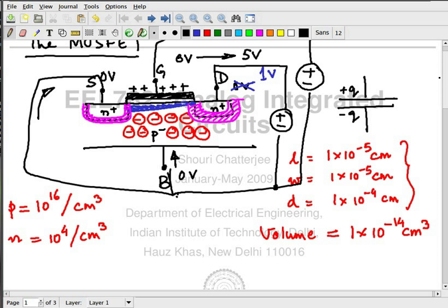This current is more probabilistic than anything. Okay, there's a small probability that there is going to be a current. So if there are 1 million devices that you are talking about, then one of the 1 million devices will be, let's say the probability is 1 in a million, right? The probability to find a hole, in spite of all this, is given by the minority carrier density you computed to be so much. Okay, it's not 0, but it's much less than 1, which means that there is a small probability that you will find a minority carrier over there, which means that if you have a million devices, then some of those will have a few, so that will give you a small amount of reverse leakage current. Okay, nothing else. If you're talking about a single device, there's nothing, no reverse leakage.